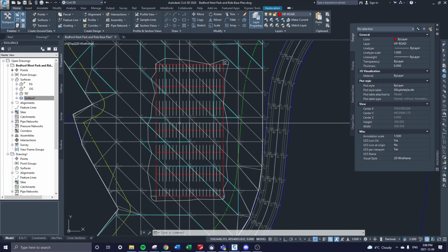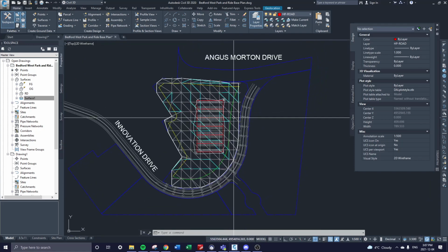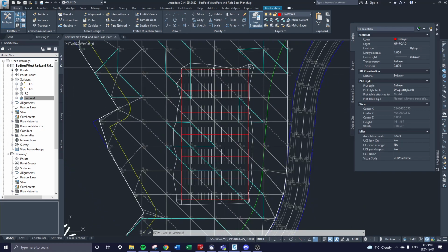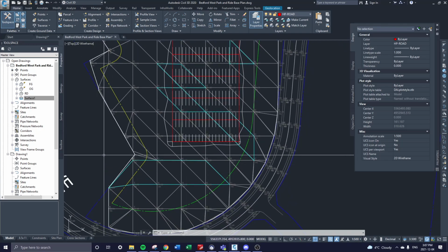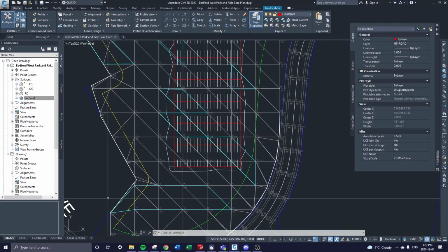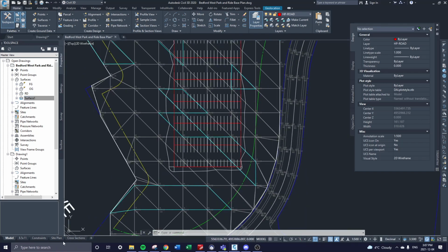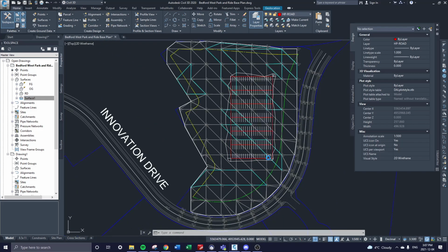If you want to advance, definitely take a look at Paul's videos. They are very similar. He messes around with changing the UCS. Yeah, don't do that. I don't think you have to. Just leave it at this view, get used to it. It's just north is straight up. If you change the UCS, that can make things a little bit difficult when you're going to be plotting things. So just try to leave it in this view as best as you can.